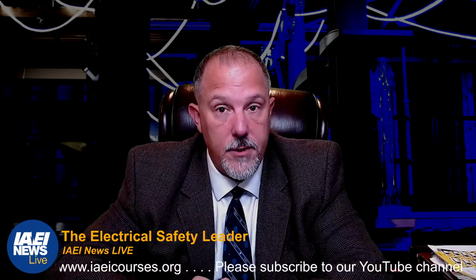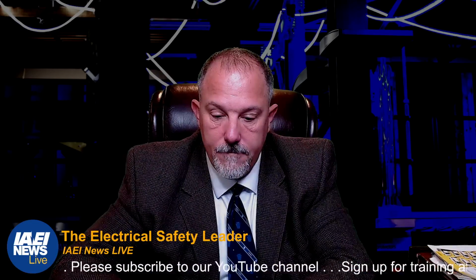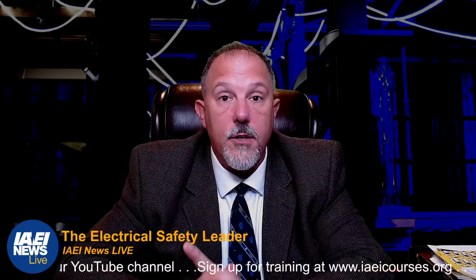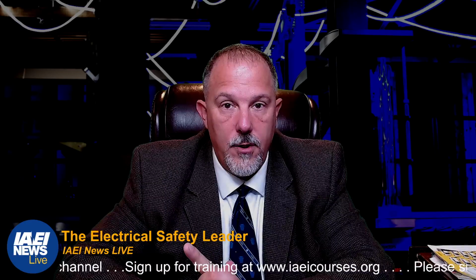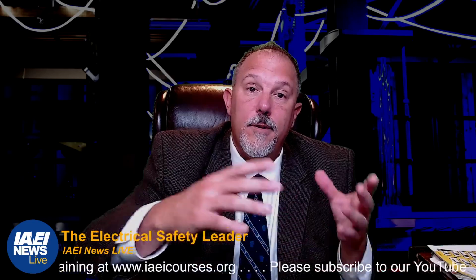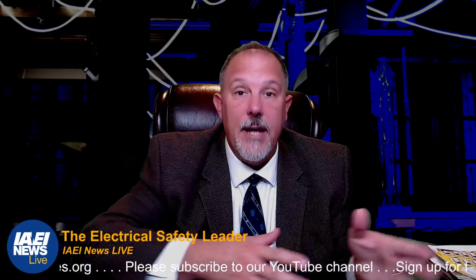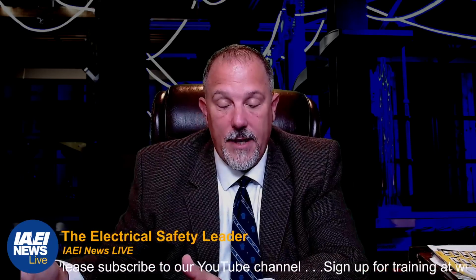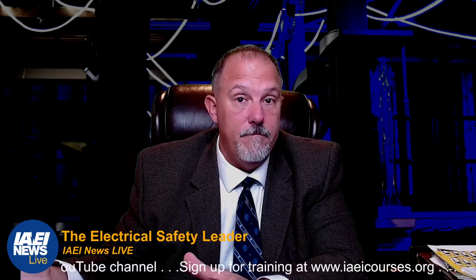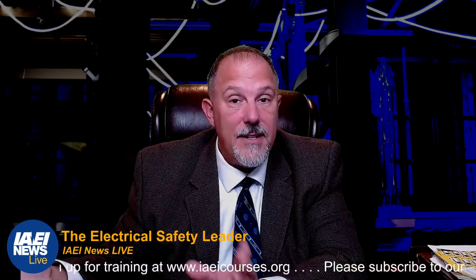Because once you have it installed and you decide that, oops, I made a mistake, then you are going to have a little bit more work to do in regard to making sure you meet the requirements for 80% rated breakers. If you bought 80% rated breakers instead of buying 100% rated breakers, then you're going to have to address the problem. And more often than not, it's not a simple fix.